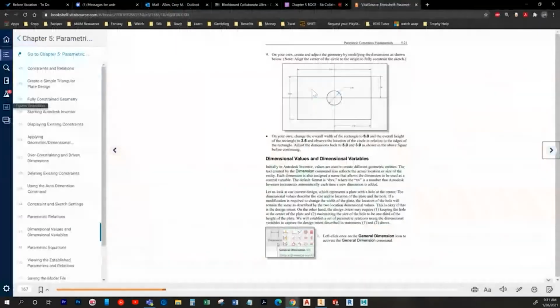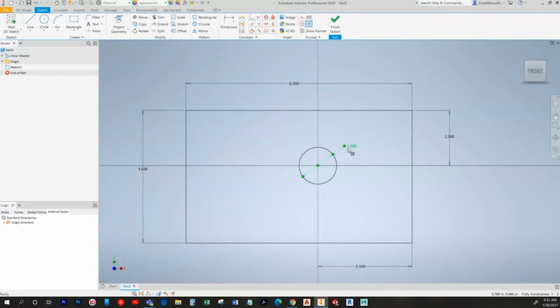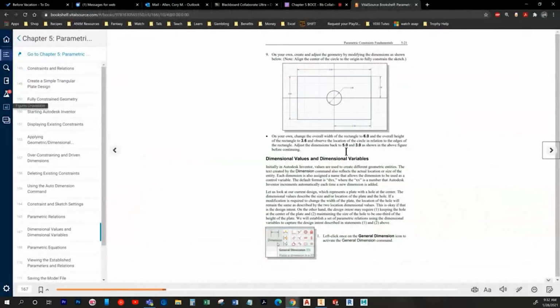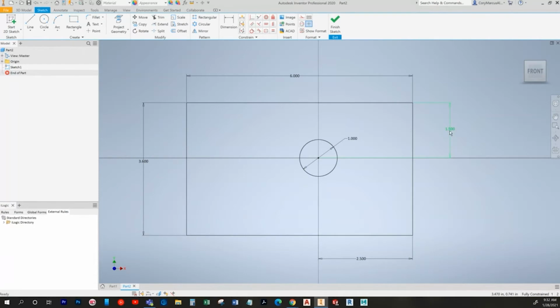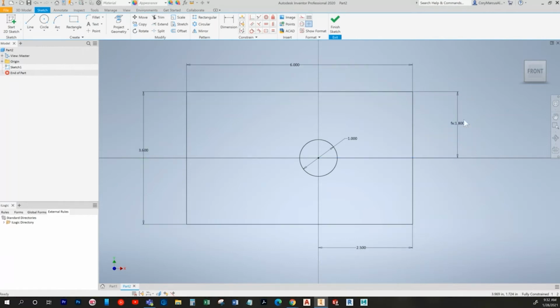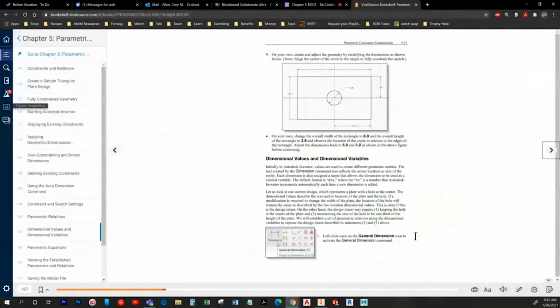It's going to become a little asymmetric. The height to 3.6. And again, now we have asymmetry in this direction. So it's just showing basically that if you're sizing something and locating it, it's going to stay located the same distance in the same direction. So the only way this is going to adjust is if you use an equation here, saying that that is half of that. That would be the way that it would stay tied to that center location. But it actually wants us to proceed with the 3 and 5 values, so I'm going to undo that.